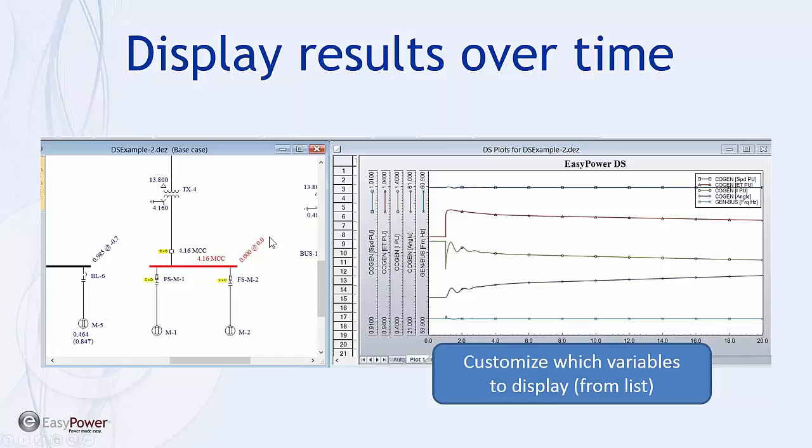The tool also has the ability to respond to different types of operator inputs. For instance, there's a double-click stimulus which allows me to open or close certain breakers or contactors, and as I do that, the system expects that I need certain results. And there's an auto display feature so that if there's a motor in the circuit, I can display the motor properties.